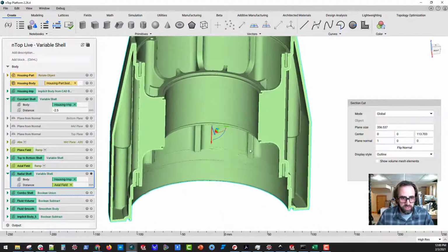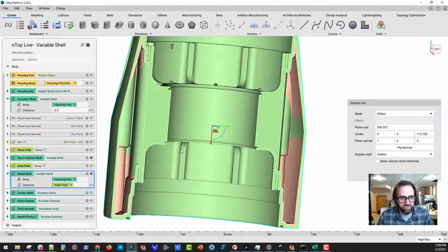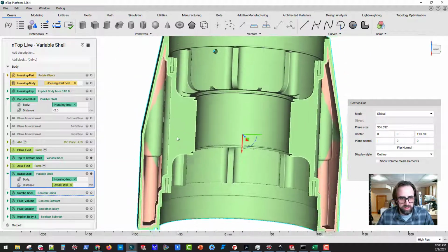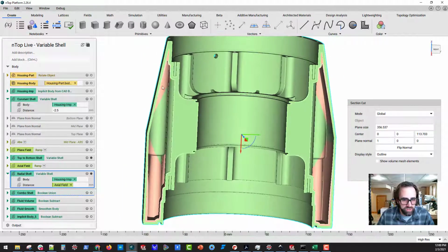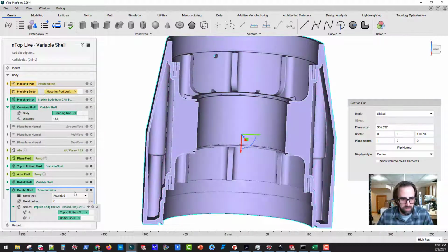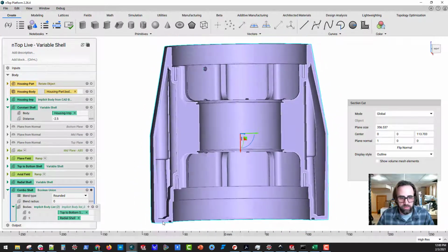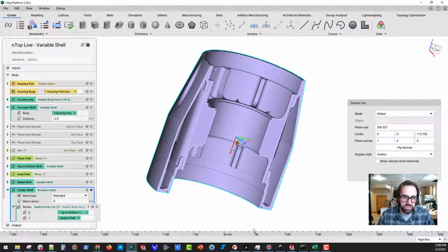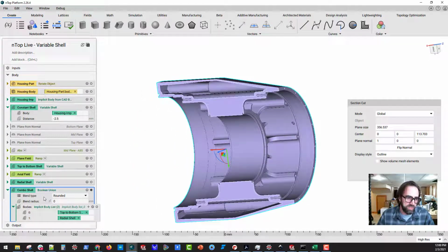Now you'll notice our part is actually solid here in the middle. And if I turn on the top-to-bottom shell, I have two different values here. In this scenario, it's nice and thick here in the middle, thin on the outside. But now in this orange, that's my original plane shell. So now I can get the combination of those two by simply unioning those two objects together. And now you'll notice I have this purple value. I have solid in the middle, thick at the top and the bottom, and overall this is going to meet our objectives for this interior volume. And that's quite easily done.